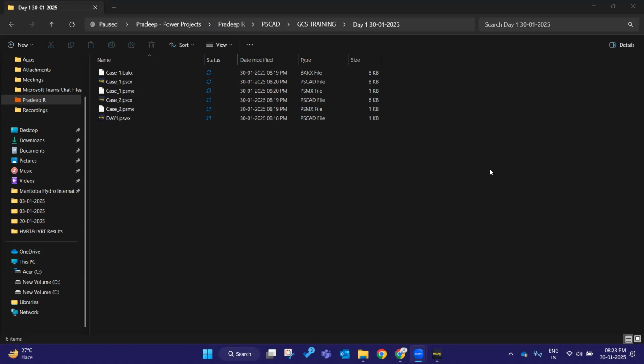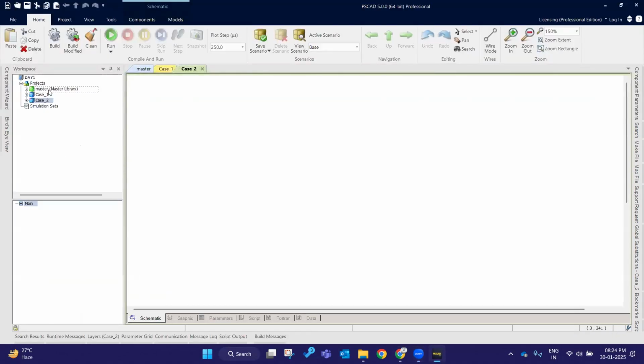After creating the workspace, do we have to press consolidate to combine both cases? No need. Upon creating the workspace, if you save that workspace, that alone is enough. Automatically the entire cases, see here, for now there are only two cases in my workspace.